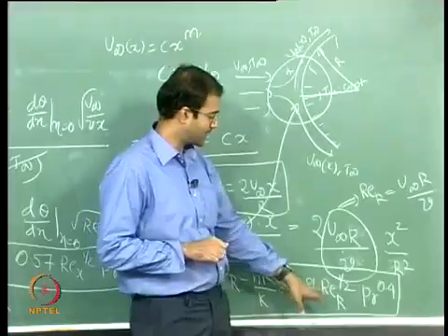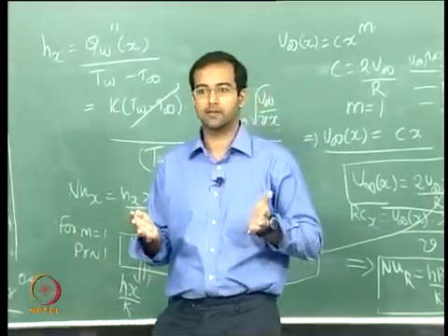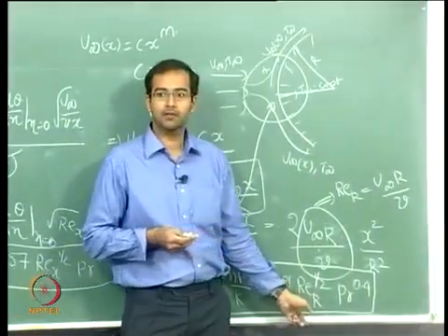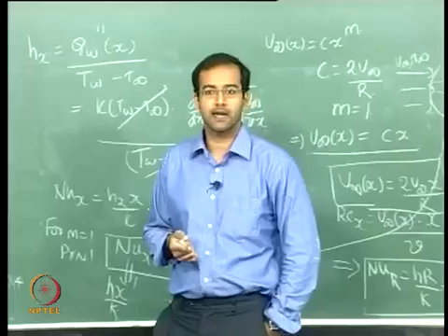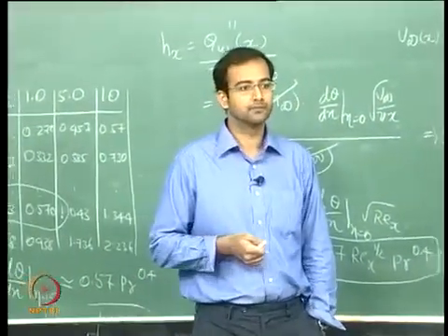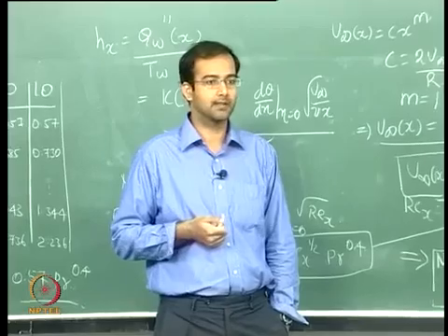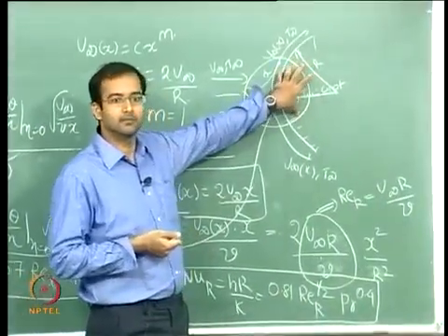So you just ask what the stagnation point Nusselt number is. Based on the free stream Reynolds number and a particular value of the Prandtl number, you directly get the Nusselt number in the stagnation region of a cylinder. You don't look at the local variation of the Nusselt number, because the stagnation region is a very small region, correct?